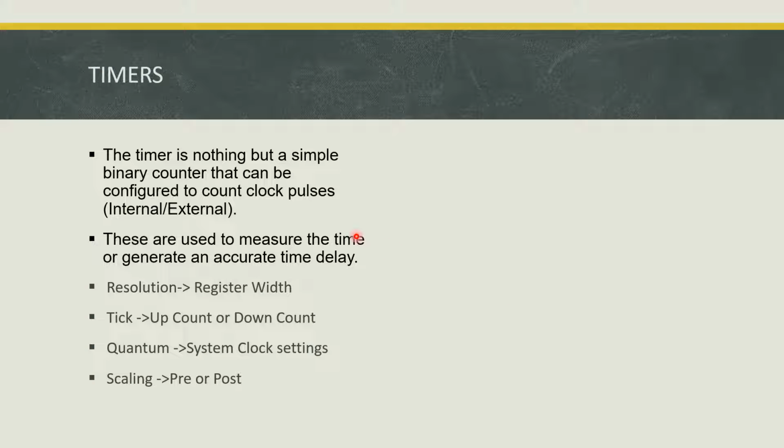Timers. A timer is nothing but a simple binary counter that can be configured to count clock pulses. These are used to measure time or generate an accurate time delay. In PicSimLab, for the board PIC16F877A, we have three timers: timer 0, timer 1 and timer 2. For our project microwave oven, we are using timer 2.